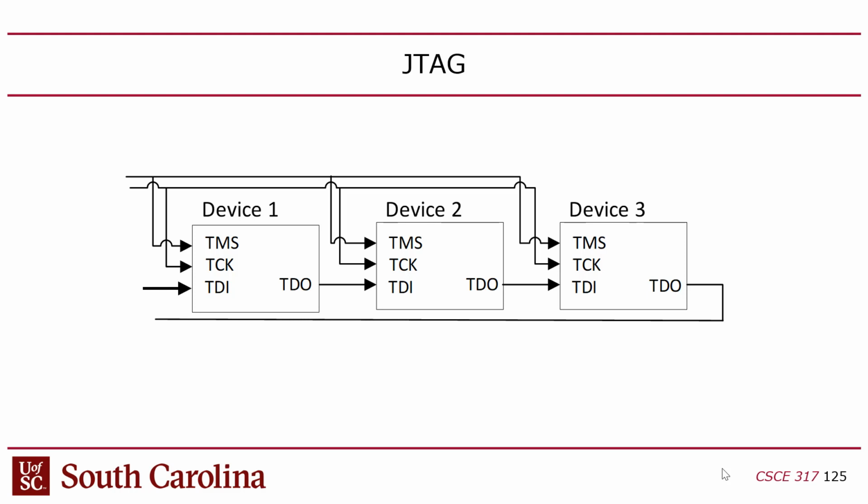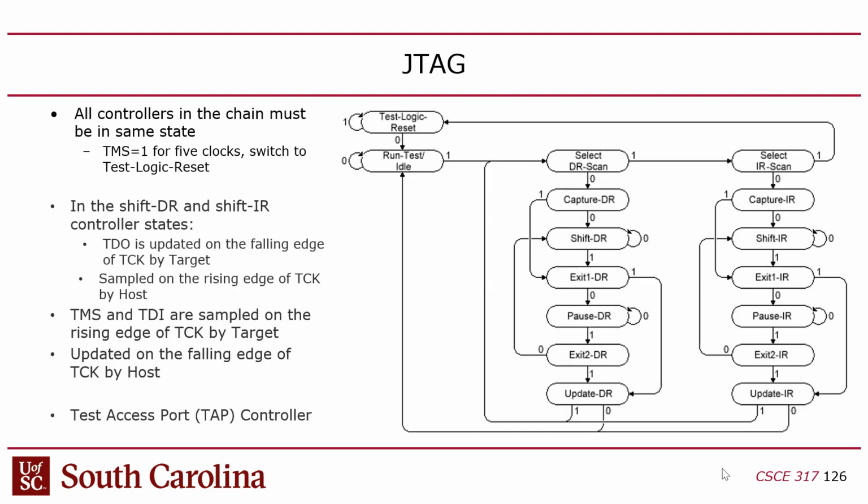you can put these devices into a specific mode, right? You could put it into an address mode or a data mode. The address mode is where you set the address. The data mode is where you read and write the data, right? And that happens through a sequence of bits that comes in through TMS. How long is that sequence? Well, it actually varies. It depends on what you're trying to do.